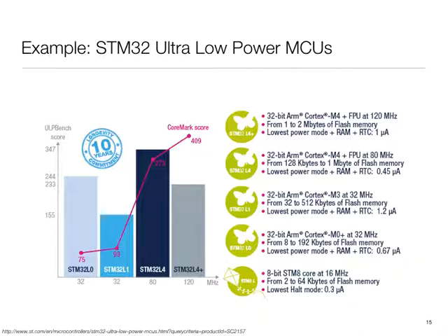So the mindset here, every data structure and all matters. You have to kind of count things. You have to make sure your stack will not overflow. You have to make sure that if you are dynamically allocating a data structure, you will actually have space for it. And there are no protections. On your regular computer, if it overflows, just that process dies. Here, the whole thing will crash. So the mindset on how you program these things changes. This is often called bare metal programming, because you are literally working right close to the hardware.